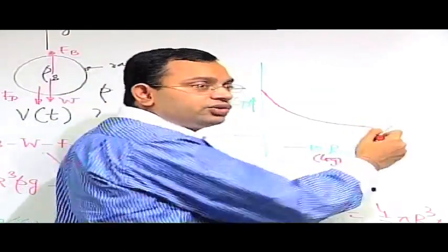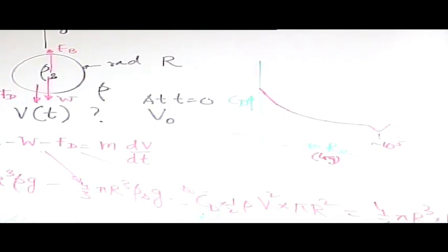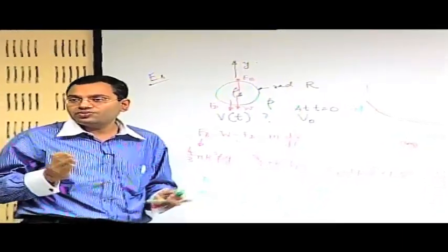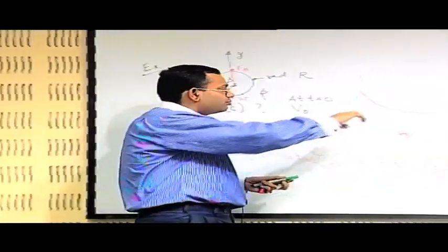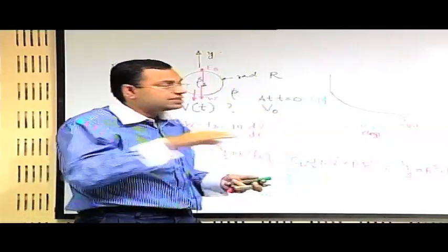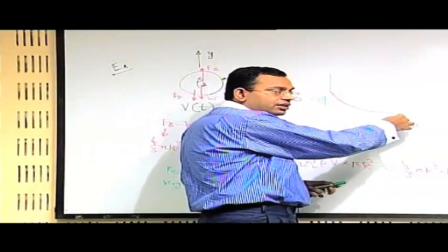Now, what happens here? Here there is a transition to turbulence. Because of the transition to turbulence, the boundary layer separation is delayed. We have seen that when the shape of the body is important in terms of form drag, boundary layer separation is what matters, because early separation will induce a lot of form drag, but later separation will reduce the form drag. So, when the boundary layer becomes turbulent, the separation is delayed. So, it reduces the form drag, and since at very high Reynolds number form drag is what is important, the reduction of form drag is what is prominent here.